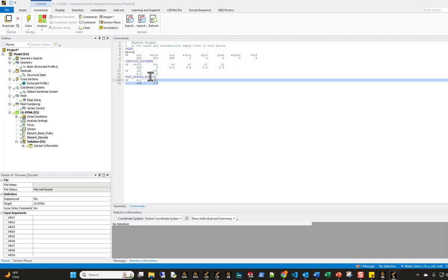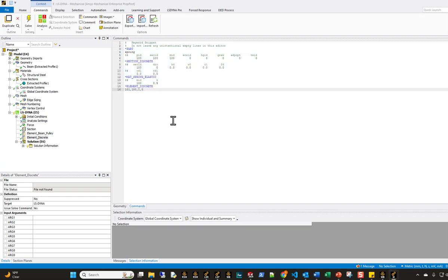This creates a part which is going to be used as a discrete element, and the discrete element is created by using the element discrete card down here. Right, so element discrete is going to have the ID 101. Reference to the part ID 100, and it has a node ID 1 and a ground of 0. So that's okay. The element discrete.